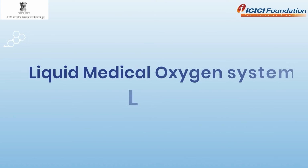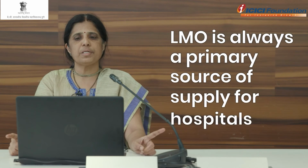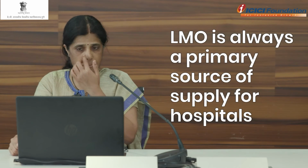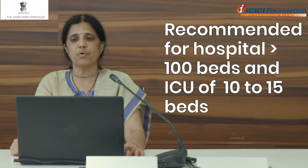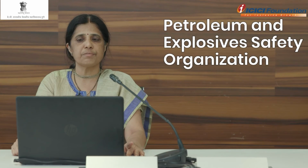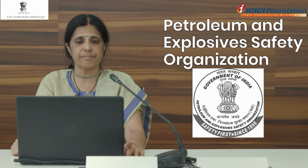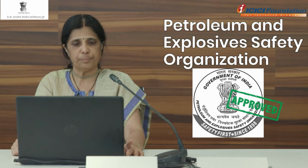Coming to the liquid medical oxygen system, fondly we call it LMO. LMO is always a primary source of supply for all hospitals. It is recommended for hospitals with more than 100 beds and ICUs of more than 10 to 15 beds. This is a pressure vessel and needs permission from the Petroleum and Explosive Safety Organization, that is PESO. PESO permission is always required prior to commissioning of an LMO.